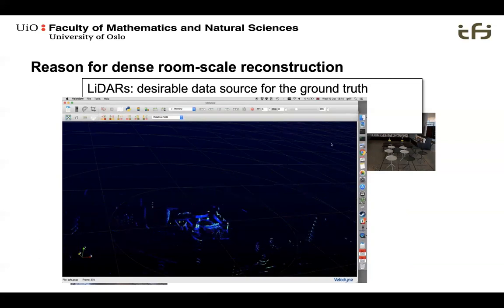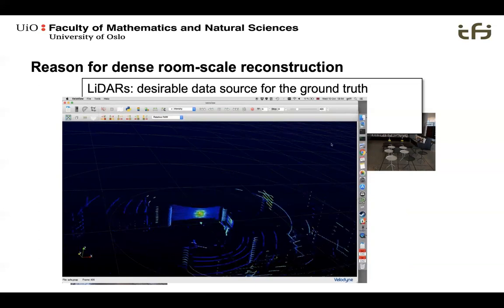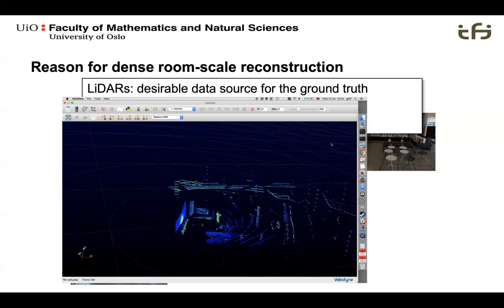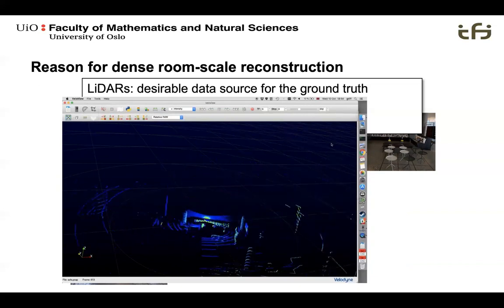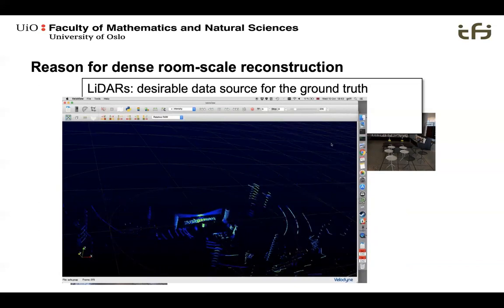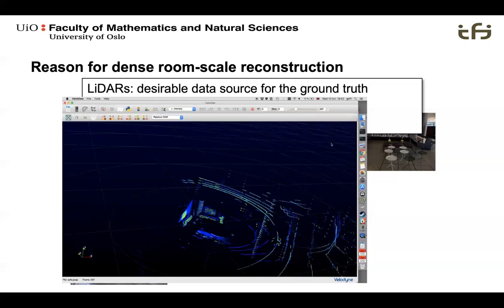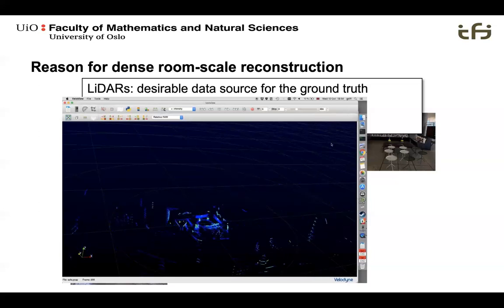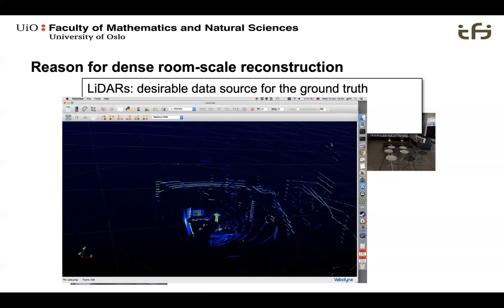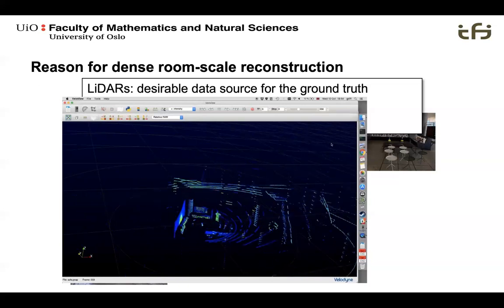As you see, you're basically getting lines. If the LIDAR is very close to something like a wall, then you get very dense lines. But for everything else that is further away, you're getting lines with a large distance because the angular distance in the vertical direction just doesn't change. The lines themselves are pretty nicely scanned because the horizontal density is very high.